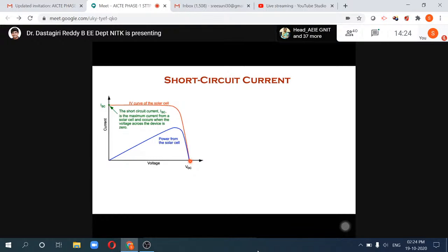And also the optical properties. In a solar panel, there is no direct exposure of the junction. There will be extra glass covering the surface. If you look closely, there is an extra layer covering it just to protect from physical damage. So that may reflect some of the light incident on the solar panel, which also affects the short circuit current.